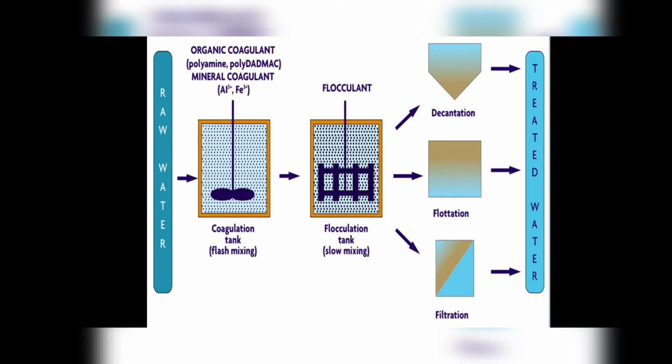Coagulation and flocculation: a rapid mix unit is usually used where the coagulant is added to the water to provide a very quick and thorough mixing. The water mixing is often then slowed to allow the water to come in contact with the forming floc and allow it to increase in size. The continued mixing must be gentle to allow the floc to grow and gain weight, but fast enough to keep it in suspension until you are ready for it to settle in the clarifier.